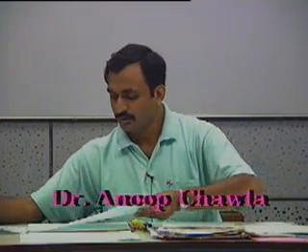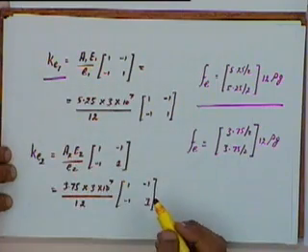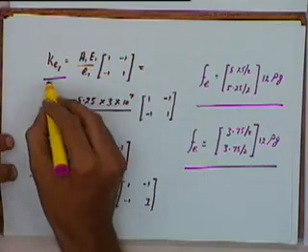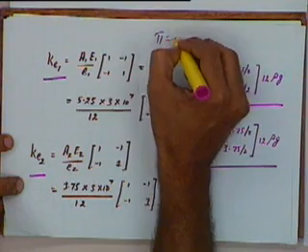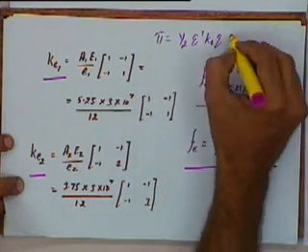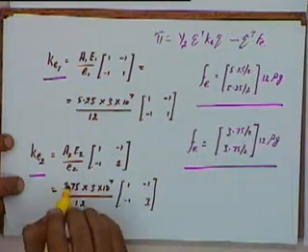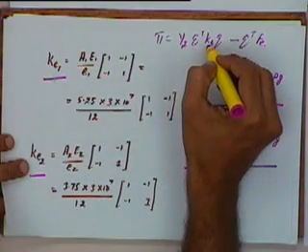As far as the elemental equations are concerned, we will get body forces given by this expression and element stiffness matrices given by these. The potential energy we have just said is half Q transpose Ke Q minus Q transpose Fe. This Ke is this expression for the first element, and for the second element it is this expression.